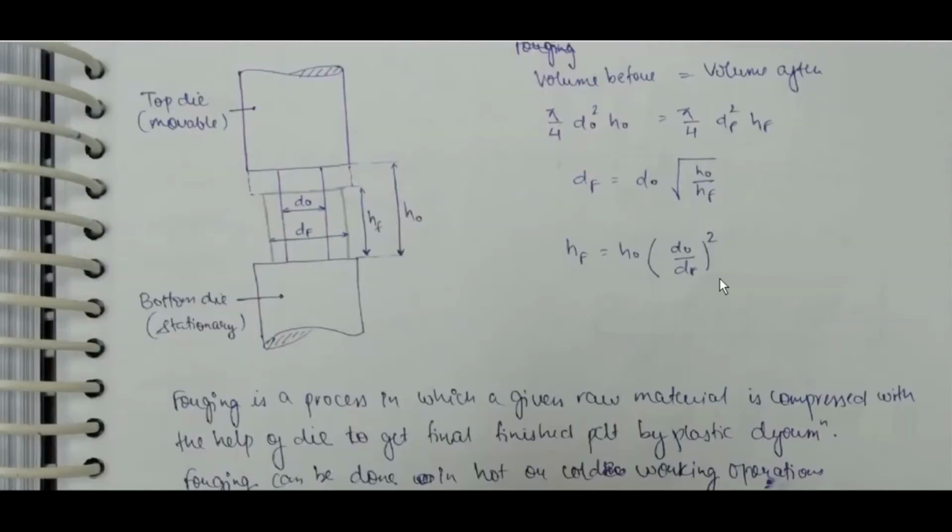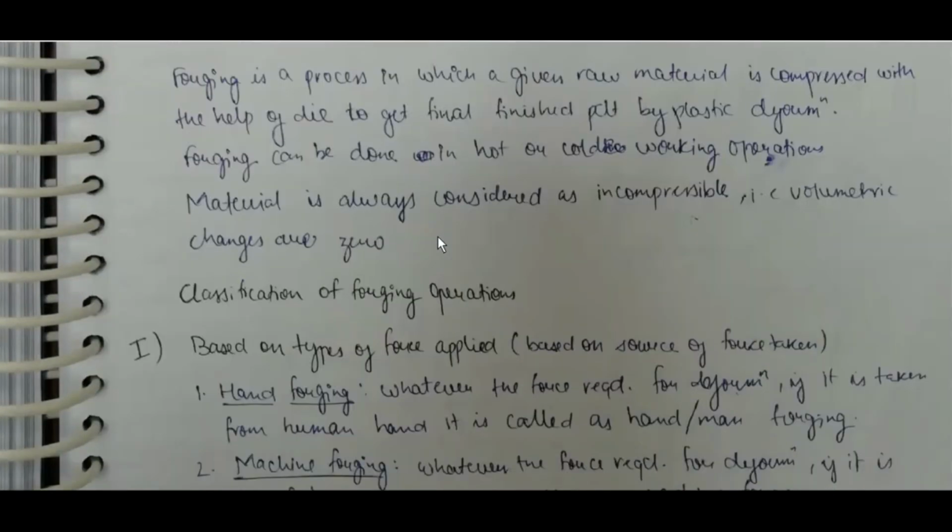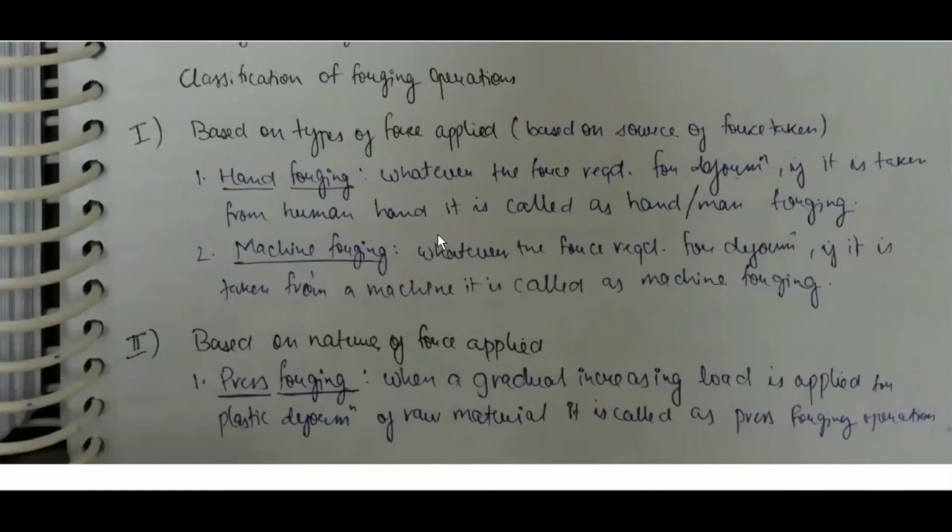Mechanism of forging: expansion force, frictional force, buckling, sticking, sliding. When force is applied by downward movement of the top die, the height of the body reduces, and to compensate for the reduction in height, an outward expansion force is generated to increase the diameter of the material.